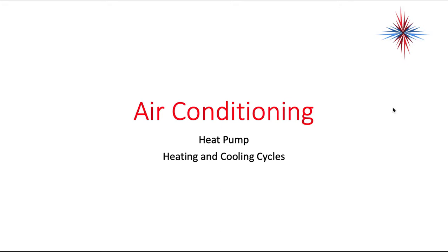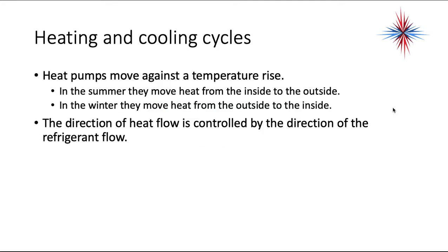Welcome back. In this video, we want to talk about heat pumps, and very specifically, we want to delve a little bit more into the heat and cool cycles and the way the refrigerant flows through the system and the reversing valve. Now, heat pumps move against a temperature rise. In the summer, they move heat from the inside to the outside. In the winter, they move heat from the outside to the inside.